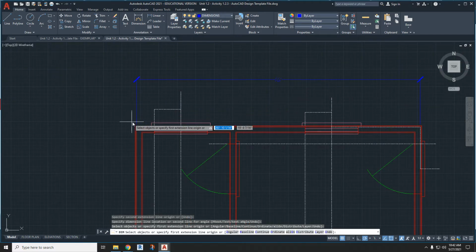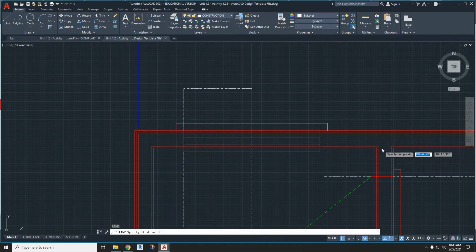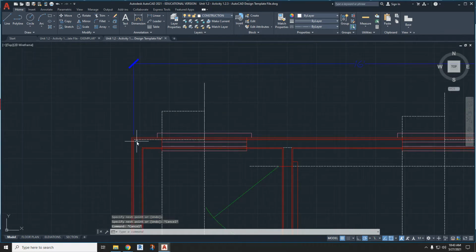And then the next layer, the middle layer, is from any wall, exterior wall. It's all dimensioning walls, so wall to wall. And what I'm missing here is, give me a second. I just realized I have to put in a line connecting this because I need to do it from the outside. For any exterior wall, it's the outside edge. For any interior wall, it's the center of the stud.